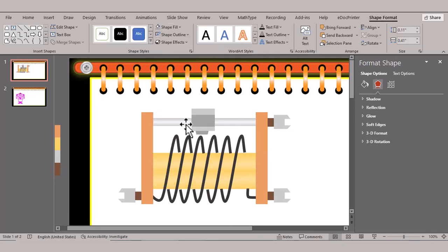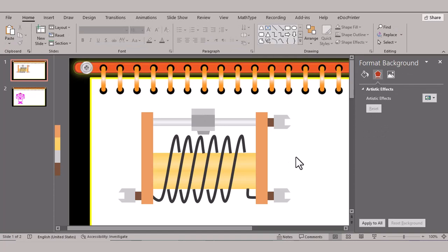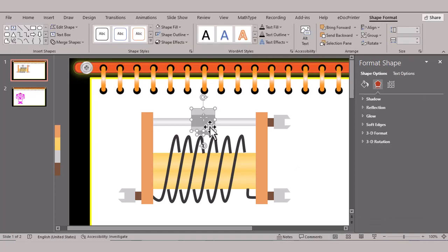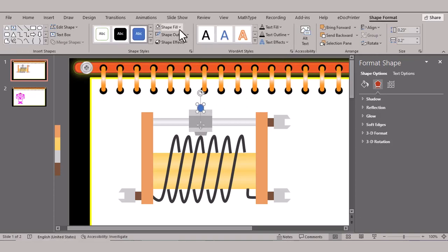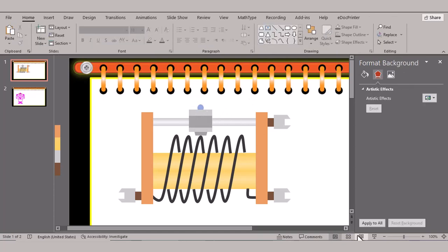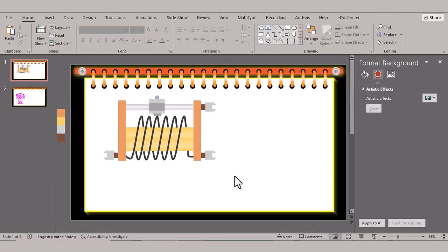The nature of a material is not the only factor in resistance and conductance, however, it also depends on the size and shape of an object because these properties are extensive rather than intensive. For example, a wire's resistance is higher if it is long and thin, and lower if it is short and thick. All objects resist electrical current, except for superconductors, which have a resistance of 0.